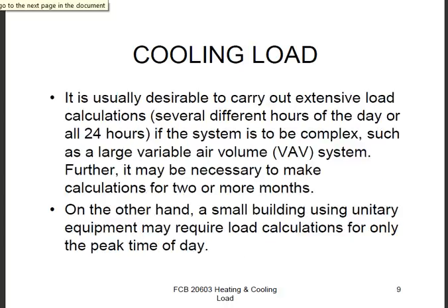It is usually desirable to carry out extensive load calculations for several different hours of the day, or all 24 hours if the system is complex, such as a large variable air volume (VAV) system. Further, it may be necessary to make calculations for 2 or more months. On the other hand, a small building using unitary equipment may require load calculation for only the peak time of day.